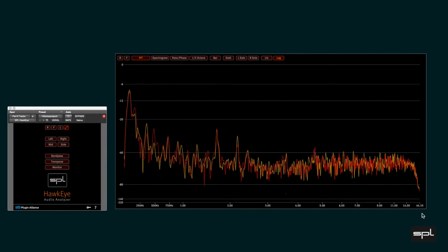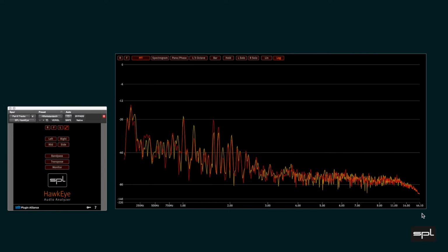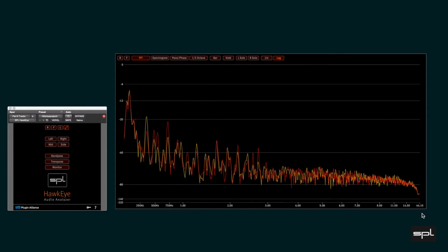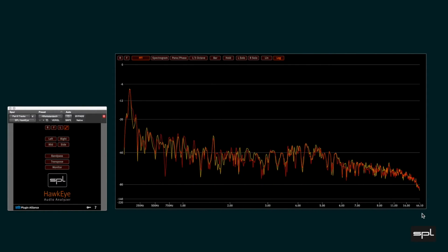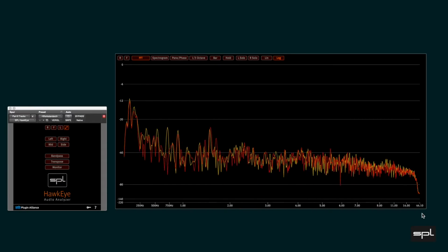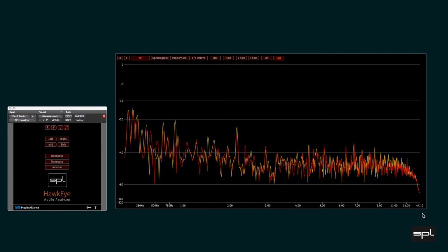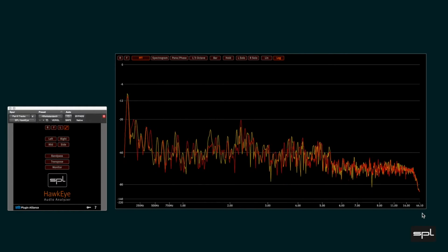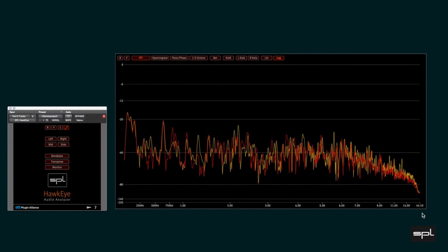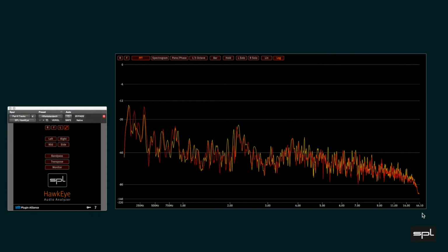In our example here we have a sample rate of 88.2 kHz, so the frequency range covered is up to 44.1 kHz. We are using a 7th order Blackman-Harris windowing function. With that, the FFT analyzer achieves an exceptional frequency separation and amplitude precision.